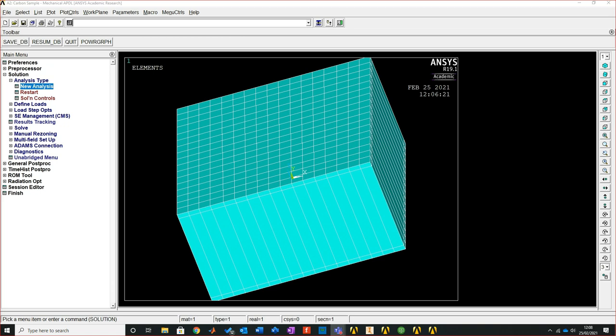Because obviously with carbon fibre, it's like a ream of paper all stacked up. If you bend that ream of paper, what it essentially does is they slide across each other. And with carbon, when it's laid over the top, the first thing that carbon always tries to do is shear itself apart. It attempts, from the first go, to delaminate. What we want to do is, can we see that happening between the aluminium and the carbon, or I should say composite material. Right, so I'm going to go to solution, and from here I'm going to define loads.